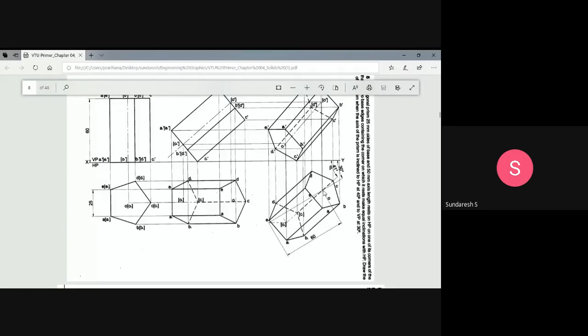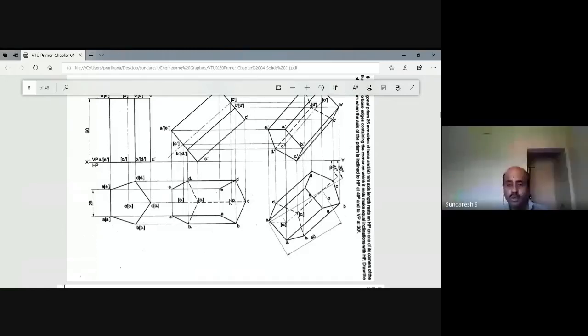Now we have got O1 on the 30 degree line. With O as a center and the radius equal to the apparent length O1 in the second position top view, cut the locus line. Draw the arc for the locus line. So that represents the actual O1 form.